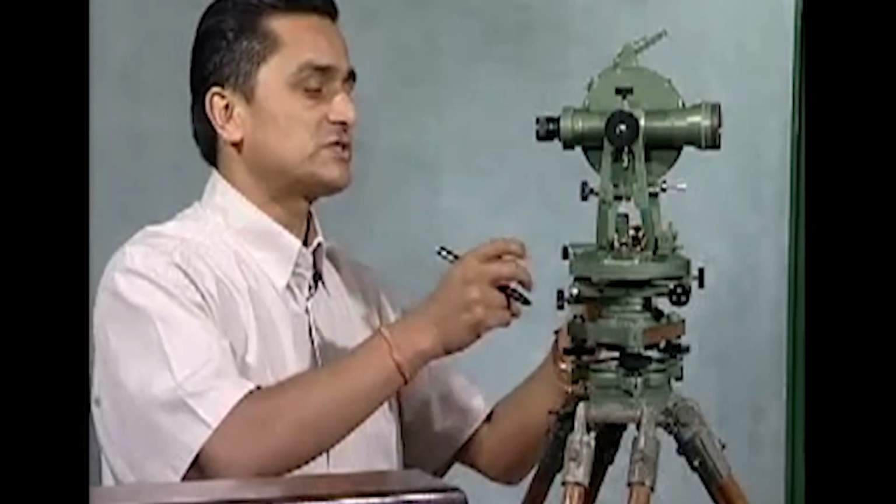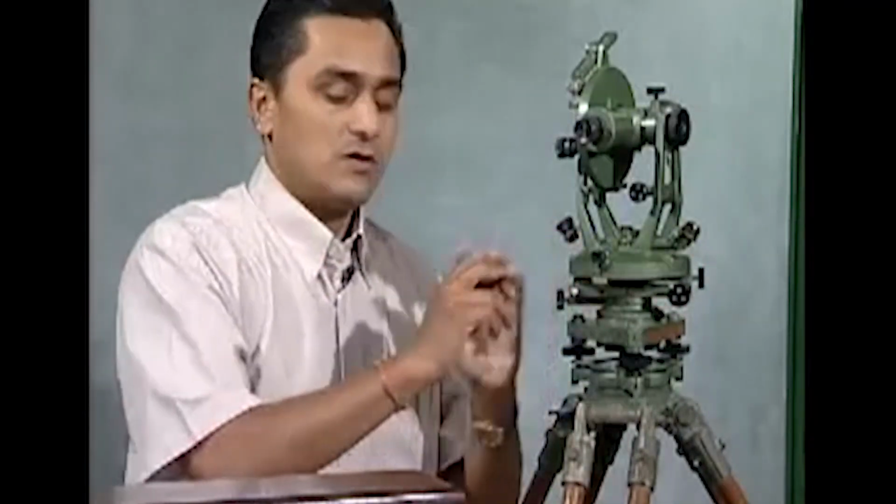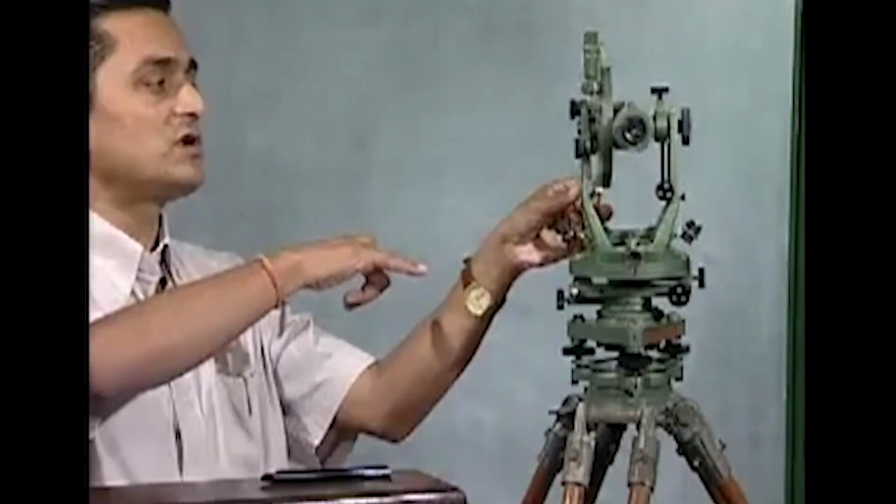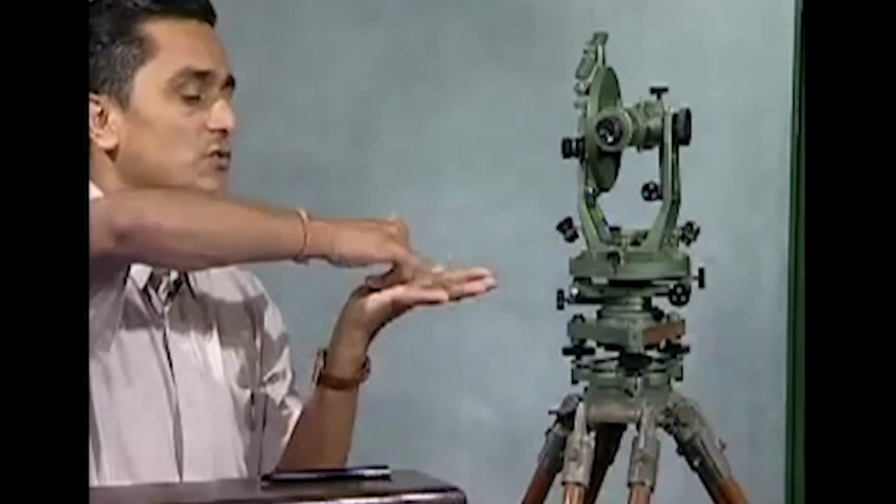Okay, so very first step. Right now you have to follow with me what I am doing. You have to imagine what is happening in the instrument, because we have already discussed the construction of the instrument. I clamp the lower one, I unclamp the upper one. Now I can rotate my instrument. What do you think, are the readings changing or not? If I look through it, yes, they are changing, because the lower one is clamped, the upper one is free to rotate, and if I am rotating my telescope, it rotates like this.